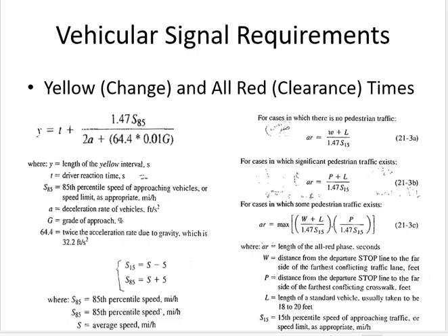Okay, we said that we calculate everything for what? All these timings are on the basis of which volume? The peak volume, but for the critical lane, and that critical lane would be left turning. So then the width of the intersection is not this. It's this, the whole path. So this depends upon the movement and the intersection size.